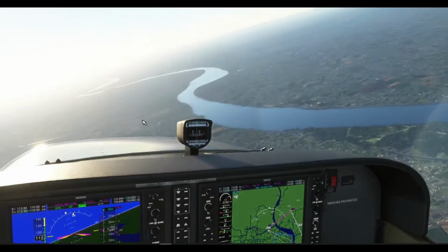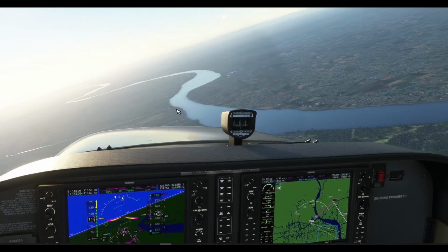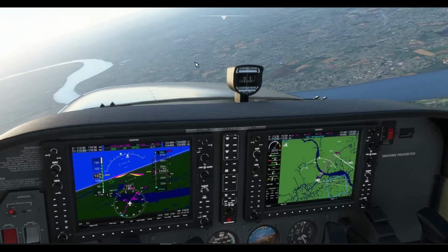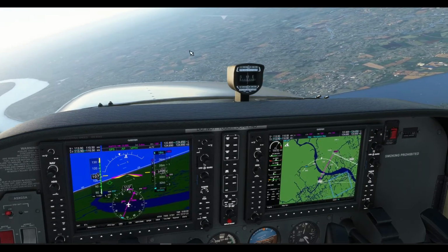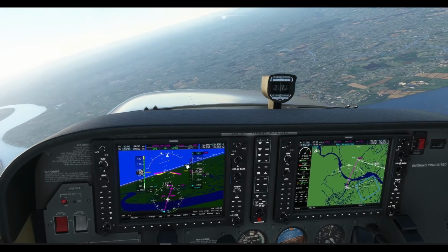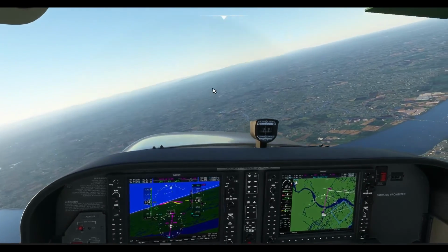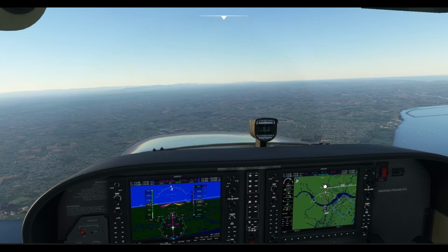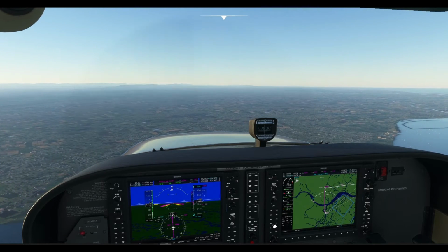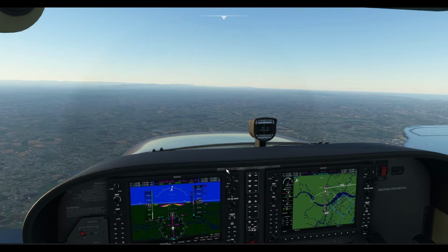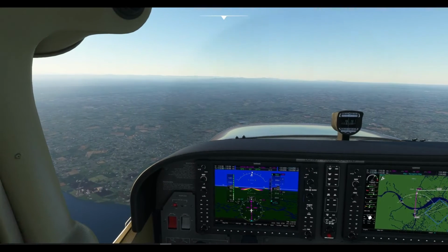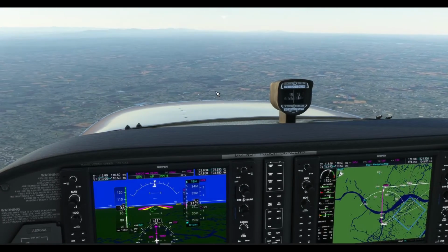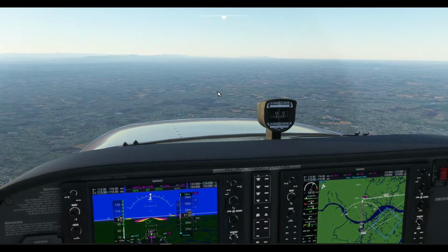I'll just reduce my speed because during the descent speed can increase. I'll just reduce my RPM actually. So yep, that would be fine. Yep, descending. After passing Aldrin and before Kanya, I will select the approach button. And if I see that there is a bug present in MSFS, I'll just press the VNAV path in that case. Or if that also fails, I'm just going to do a manual landing here in this scenario.